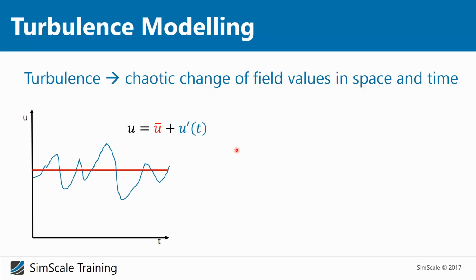So instead, and this is called direct numerical simulation, today it's maybe possible to do direct numerical simulation for a flow, two-dimensional, three-dimensional flow around a cylinder at a very low Reynolds number, but not for a full car. It's not possible. So we use turbulence models. And the turbulence model uses the following simplification.